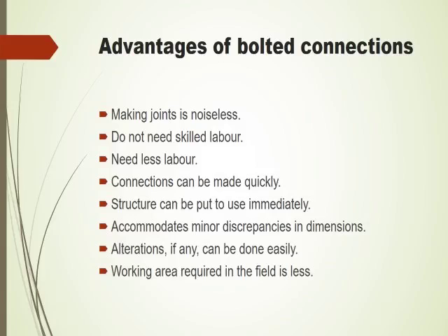And alterations, if any, can be done easily. Like I said before, in the riveted connections, removing rivets is a costly job, and it is not at all easy, and it needs skilled labor also. But here, as they are bolt and nut connections, we can loosen the nuts easily, and we can alter the structure however we want.